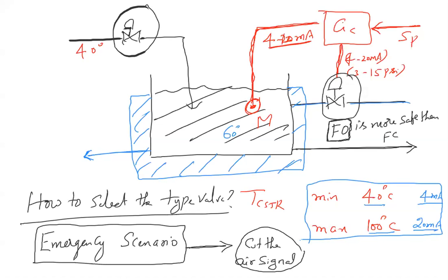Suppose you take a compressor. Inside the compressor there are small pumps, because the compressor generates heat. How do you remove that heat? Using lube oil, as you call it in plant terms. That lube oil circulation is done by small pumps sitting in the compressor. Cooling water can't be used because the heat generated is extremely high, maybe 200 degrees, so water will become vaporized. That is why we use lube oils.